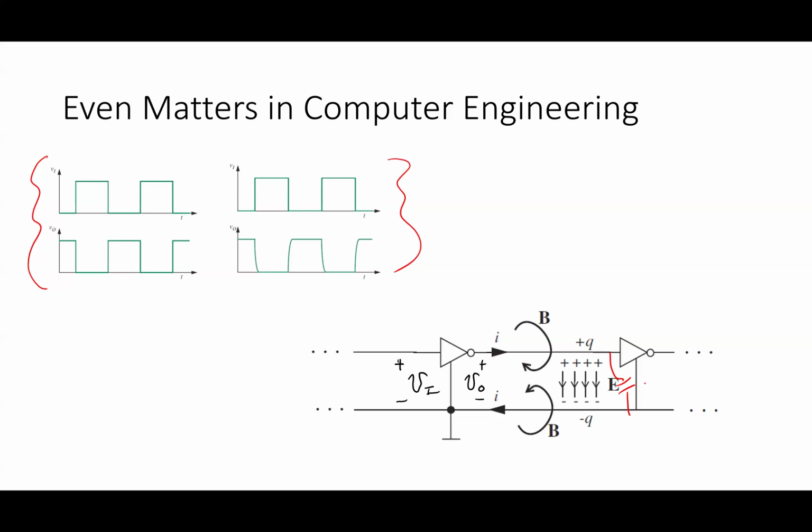That stuff matters because how fast a digital system can operate is limited by things like these capacitances. And in reality, there's probably even some inductance to that wire, which may cause problems. And why does this matter? The reason it matters is I get this rounding effect, but it tells me that I can only make that clock waveform, that input waveform, be so fast.